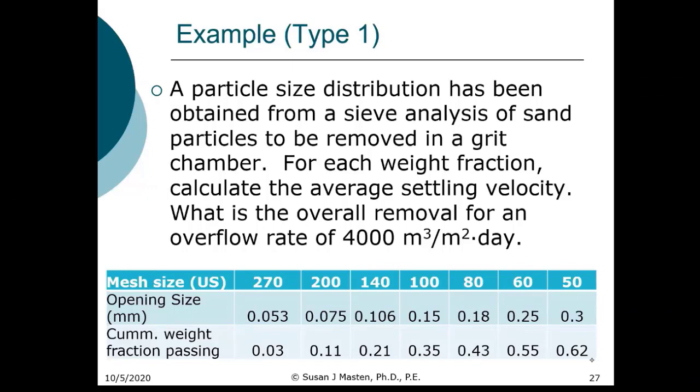So what this tells you is that 3% of this sample was smaller than 0.053 millimeters. 62%, shown here, 62% is smaller than 0.3 millimeters.